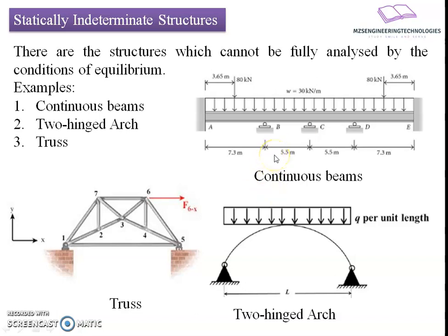This will define the degree of indeterminacy. It depends upon the number of forces which are unknown. It goes on increasing as the number of unknown forces increases. For this structure to be analyzed, we make it a statically admissible structure by removing one of the forces or unknowns which are leading to this indeterminacy.